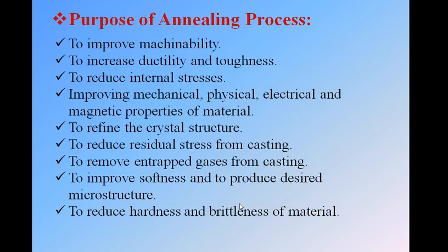See, what is the purpose? If we talk in general, when I anneal the material, when I soften the material, what will happen? As we know, as I soften the material, its hardness will decrease. As hardness decreases, brittleness will decrease. As hardness decreases, its softness, ductility, malleability, toughness, and machinability will increase. These are the general ways we can say. So we have a few points, or purposes, for which we use the annealing process. First, to improve the machinability. As we have softened the material, it will improve the machining speed.